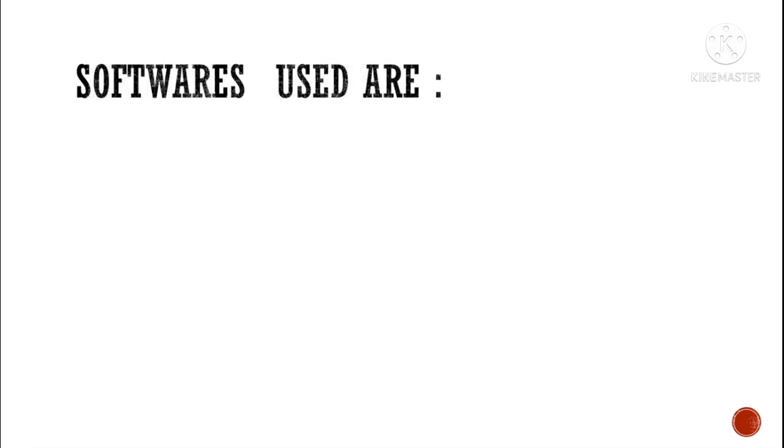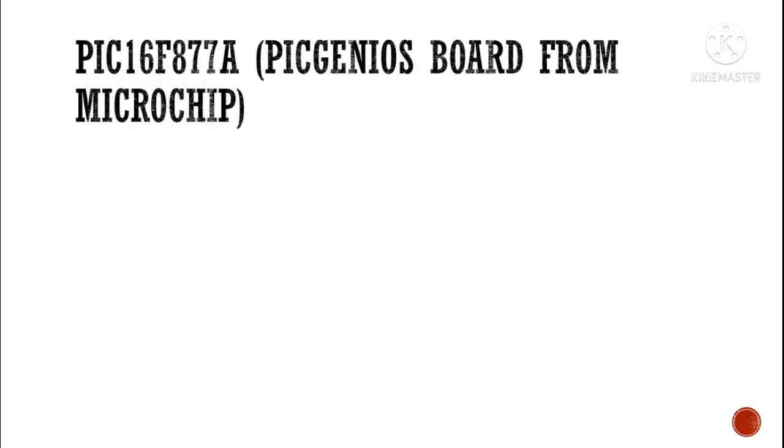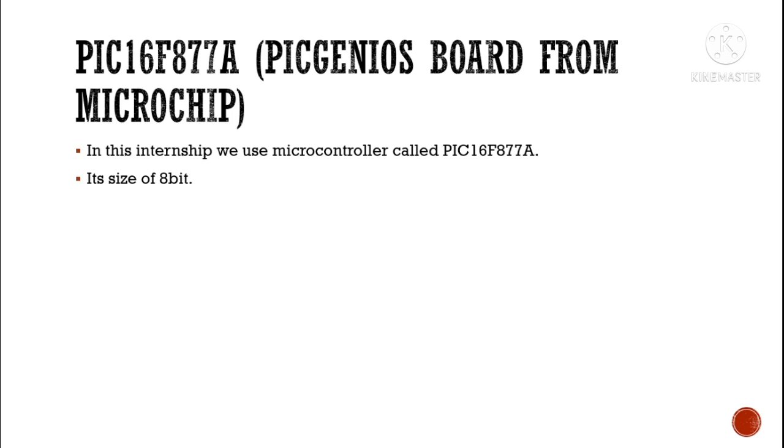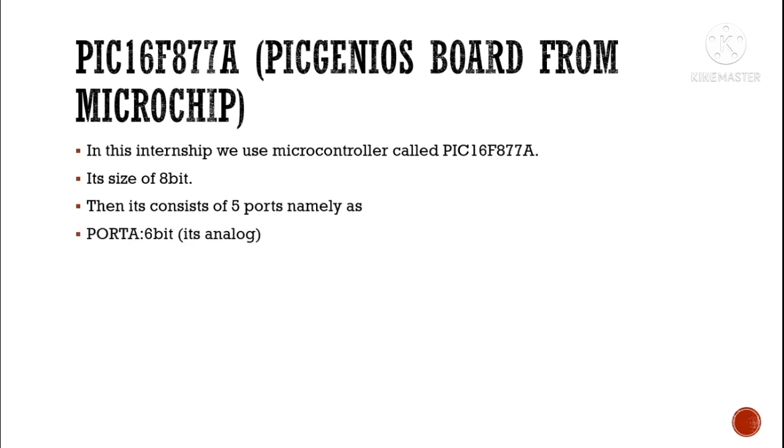The software used in this internship are MPLAB X IDE, the XC8 compiler, and PICsimLab. We use the PIC16F877A PICGenius board from Microchip. In this internship, we use a microcontroller called PIC16F877A. It is 8-bit and contains 5 ports. Port A contains 6 bits.